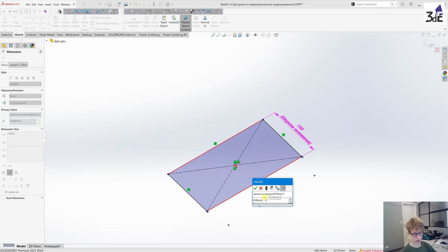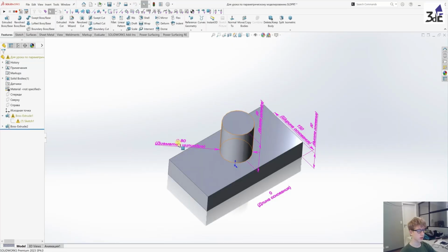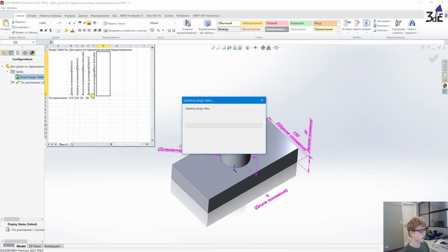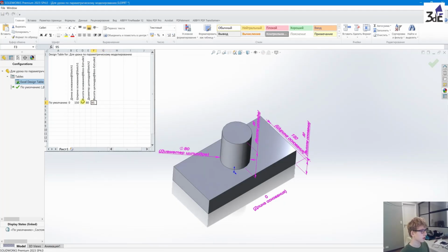This happened because in our table, the display format was set to text, and you can't multiply text. That's why we got 0. I'll undo this. I'll cancel editing the sketch. I'll go back to the table. Alright, and I'll change all the original values back to the numeric values. Here, and I will set it once again. This particular value is equal to this, multiplied by a factor of 2.